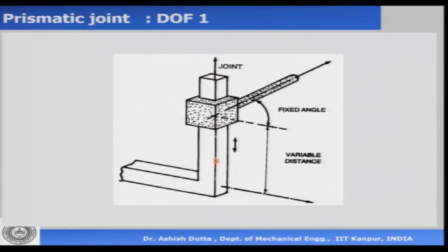So this is called the axis, and the degree of freedom is that it can translate, it can move up and down on this joint. So this part can move up and down along the inner rectangle, but it cannot rotate about the axis. Okay. So this is my axis, and the degree of freedom is a translating degree of freedom, and this is called 1 degree of freedom. So when we say 1 degree of freedom, essentially what changes when this joint moves is this distance. So this prismatic joint has 1 degree of freedom.